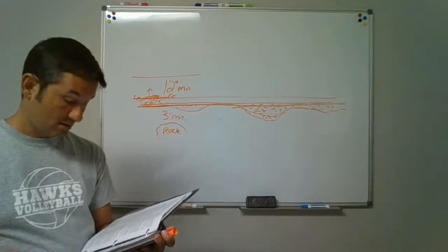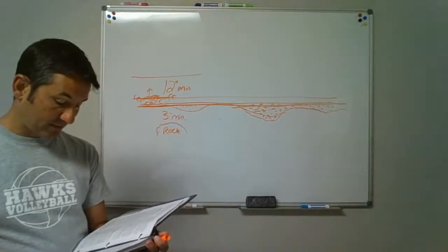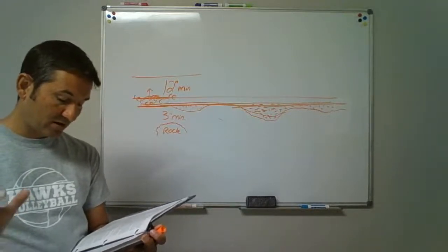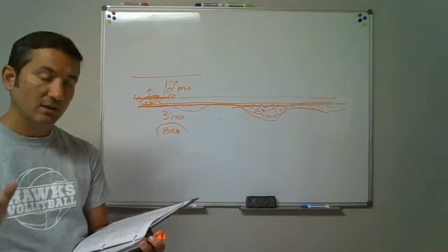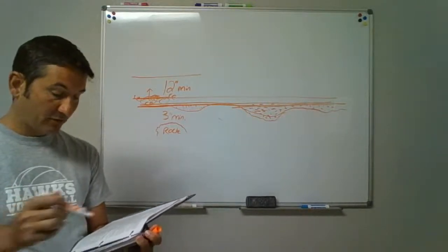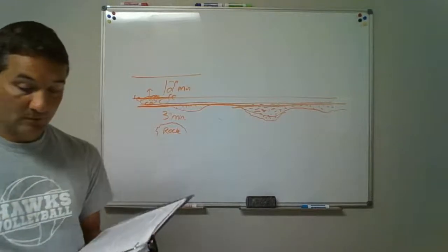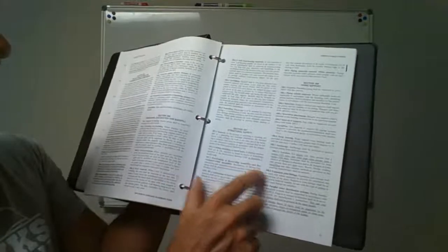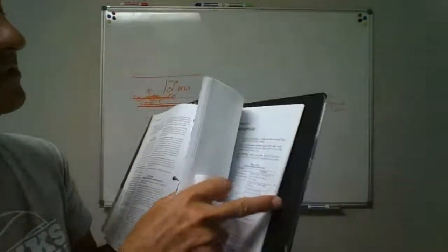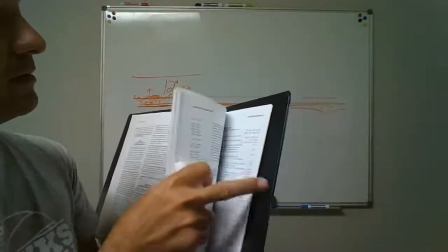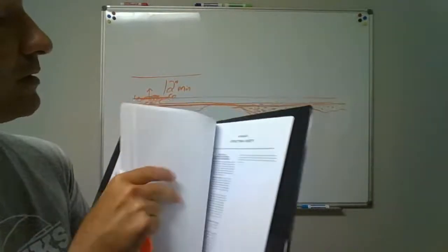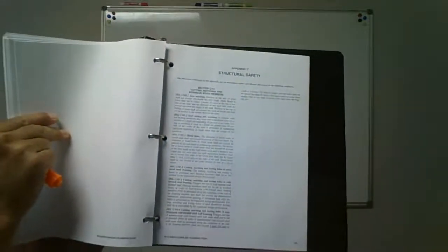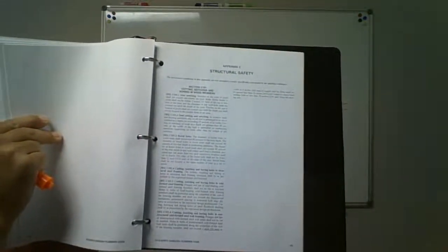Structural safety. That's going to refer you over to 307.2. It talks about cutting, notching, and boring holes in framing members. That refers you to Appendix C. So the information in there, it says, refer over to Appendix C there on page 17. Your appendixes are in the back. There we are. Appendix C, page 125. Page 125, structural safety. There's the rules there.